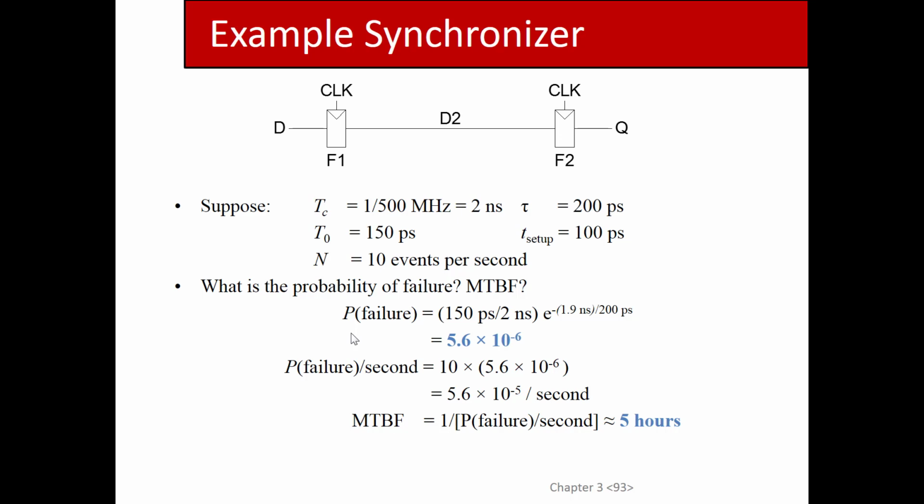Make sense? So for synchronizers, yes. Why don't you consider the hold time constraint? Well, you can't, because the timing constraints are for the synthesizer, the thing that generates the circuits, right? Normally a timing constraint is about how much you can pack into a data path, right? And people obviously want to put more in the data path because, in a CPU, the more stuff you can pack in the data path, the fewer cycles you need to perform something, right? So that would translate into a better cycles per instruction, for instance, right?